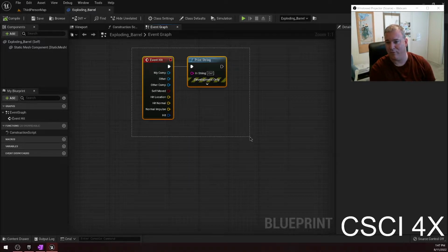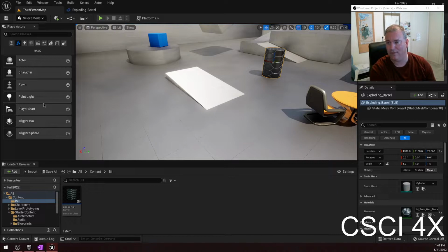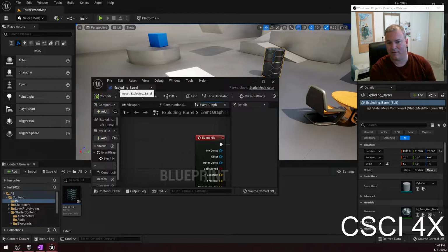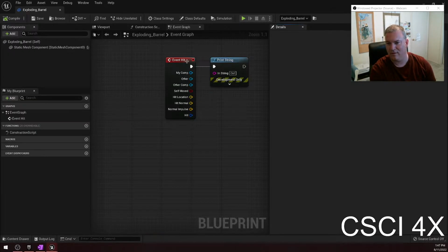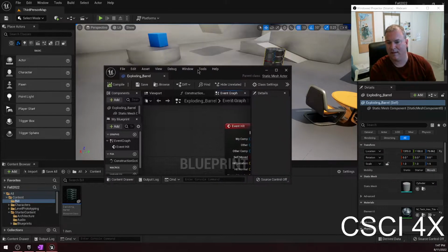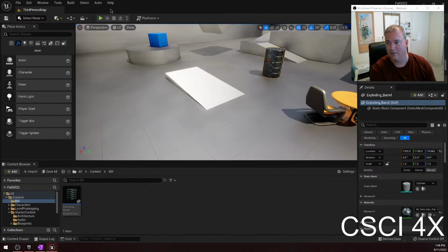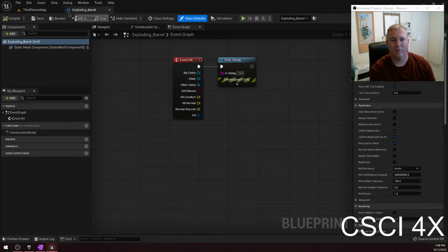You'll see me doing that sort of compulsively when I do Unreal Engine because it crashes so often. So you'll see me hit compile, save, and then I flip back to the world. I think by default for you, it's off in its own kind of tab. All of these things are dockable in Unreal Engine, so you can click and drag these tabs and resize things anywhere. One thing I like to do is take my tabs and stack them up here, so I can switch back and forth between the main map and whatever assets I have open. When I'm done with an asset, I just close out of it. If I ever want to get back into it, I can go over here and open the blueprint editor, or I could double click on it here. And then it opens right back up.